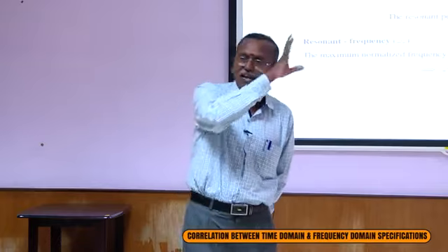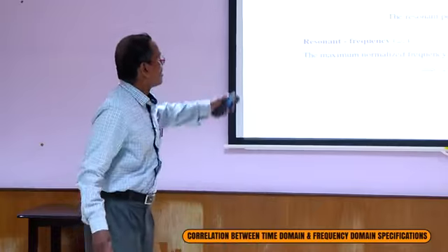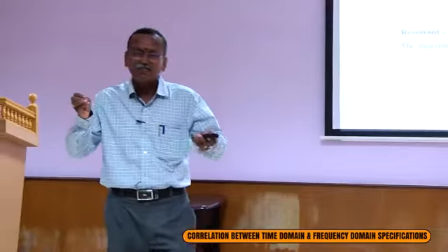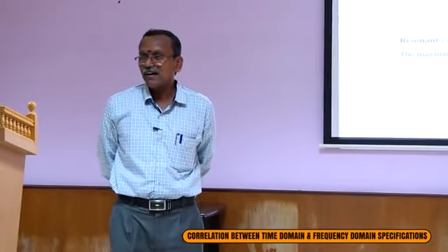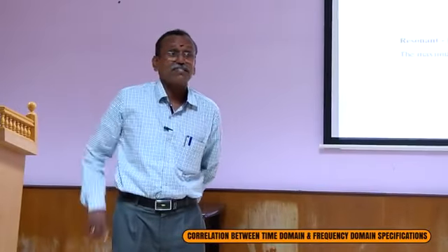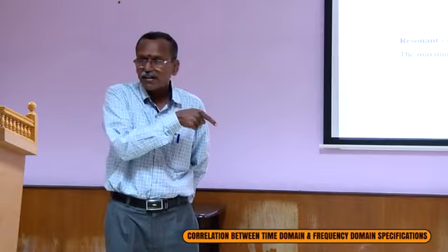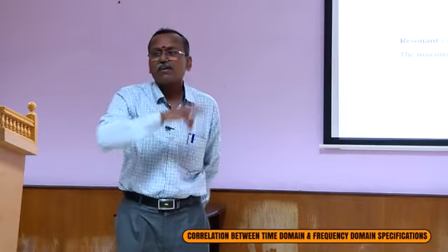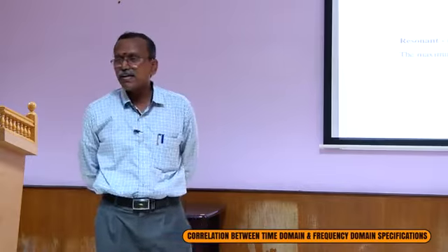So substitute that value in the M. You will get this Mr. It is a function of zeta only. But zeta is a time domain parameter, and Mr is a frequency domain parameter. So there is a correlation between the frequency domain and the time domain.